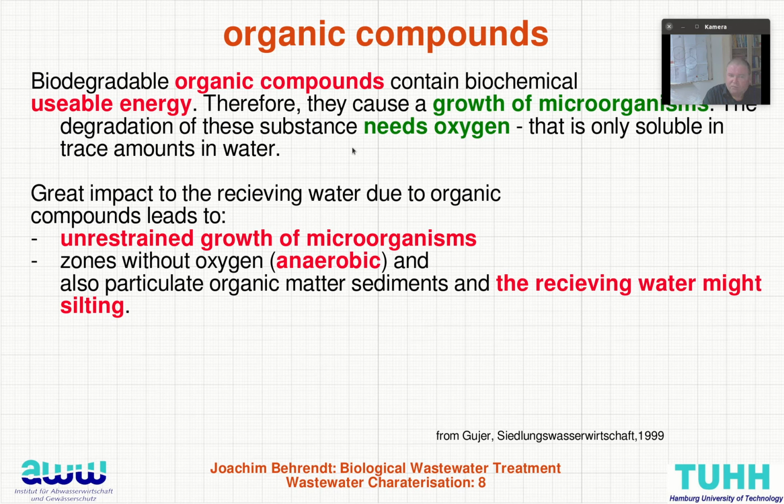Organic compounds play a big role because we want to know whether they are biodegradable. If they are biodegradable, they cause growth of microorganisms, and they need oxygen, or they consume oxygen. Oxygen is only soluble in very small amounts in water, around 10 milligrams per liter, and so it is depleted very easily.